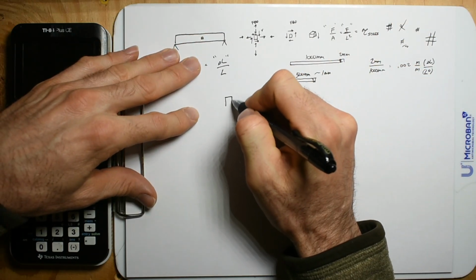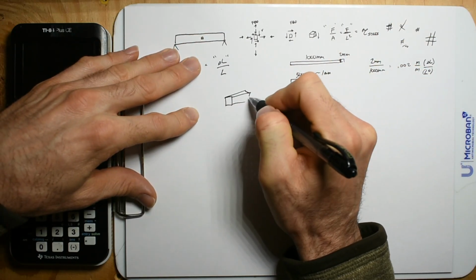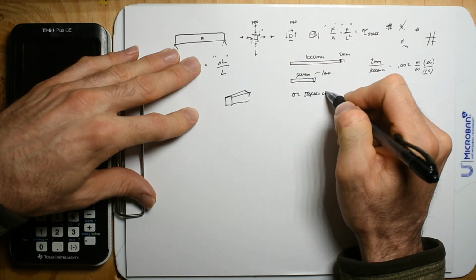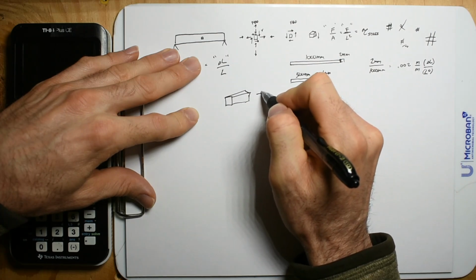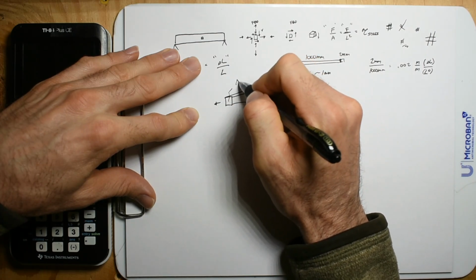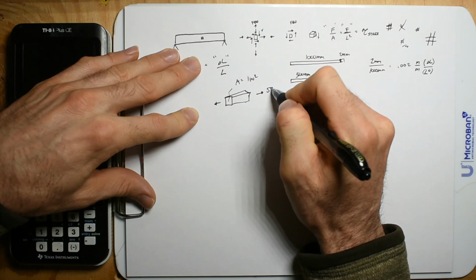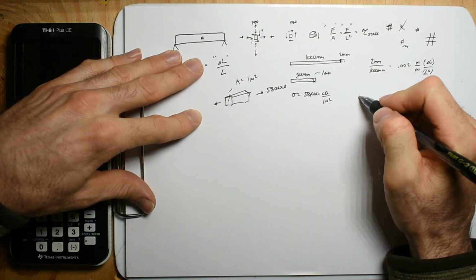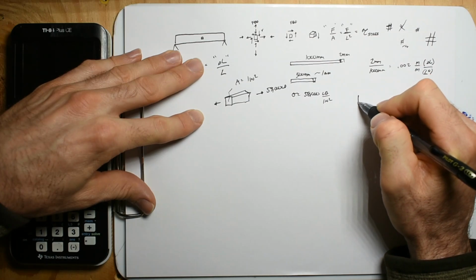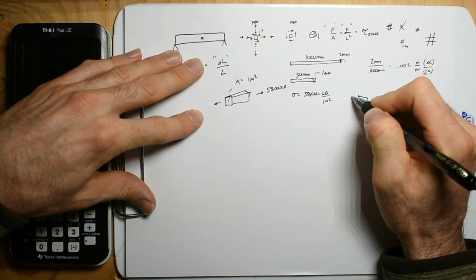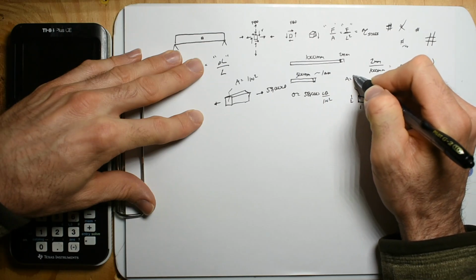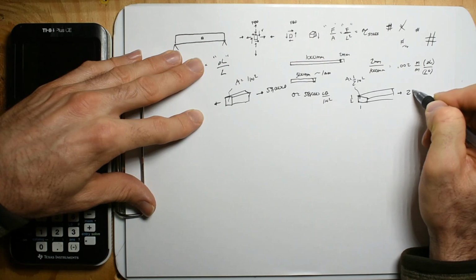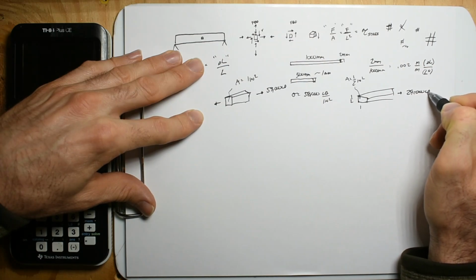If I have a 1-inch steel bar, and the strength of steel is 58,000 psi, pounds per square inch, I can put a load of 58,000 pounds in tension if the area is 1 square inch. But if this is 1 by 1/2, so the area is 1/2 of a square inch, for the bar that I'm pulling on, I can only pull 29,000 pounds.